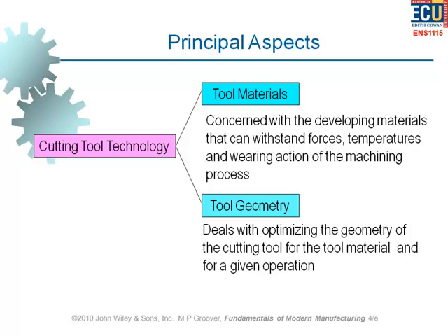How about geometry? Geometry also plays a significant role in any machining operation. In last week, we had a discussion on the theory of machining. We remember the rake angle and the shear plane angle. Those are some typical parameters which are decided by the geometry of the cutting tool. So, geometry also could play a role in the tool life and also in the outcome of the machining process.